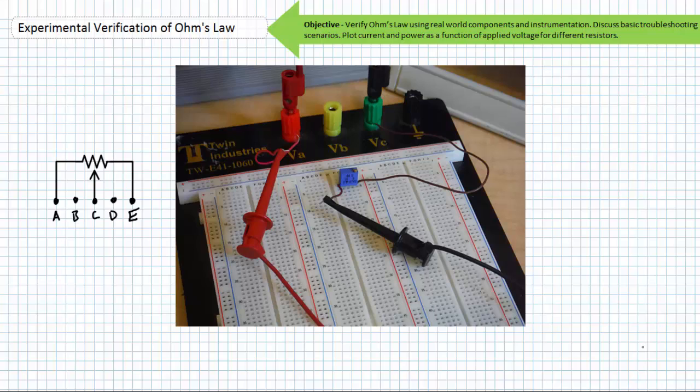If you know how protoboards work, it is immediately evident that the 3 leads of this potentiometer are all tied to the same node, because the 5 connection points in this row are all tied together via a conductive clip that is not visible to the naked eye. However, it's immediately recognizable to those that know how to use an ammeter and a protoboard. Again, you need to identify not only the proper terminals for the components you're using, you've got to deploy them in your circuit building environment correctly.